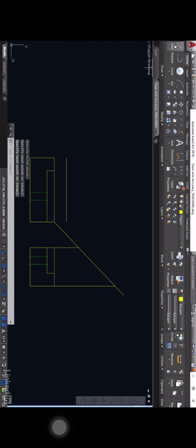I can now draw some lines that basically object snap track to the endpoints there. Now, the good thing is I can take this line away. I don't actually need it. So what I'm going to do is I'm just going to delete that. And I'm going to take my line this time. I'm going to draw the line using the line command. And I'm just going to hover over some points. If I hover there like that, and then hover over this point like that and come this way, that's where my plan view corner starts.